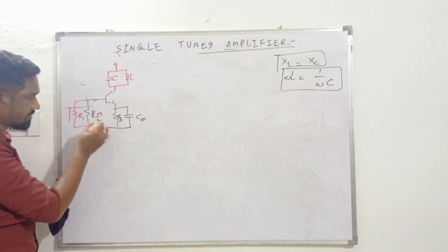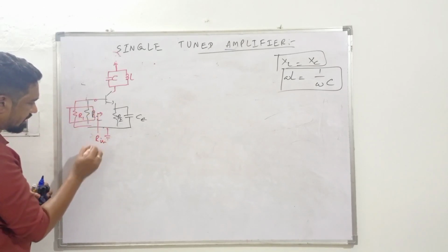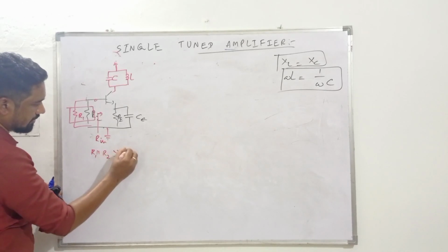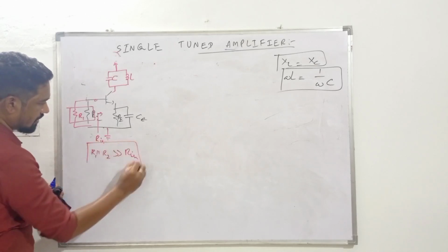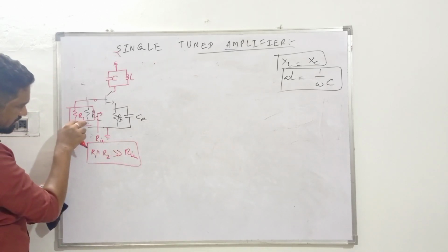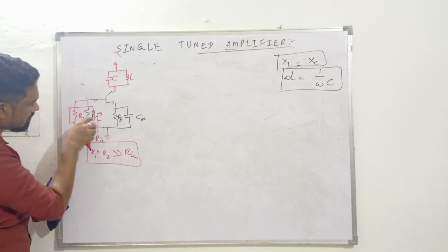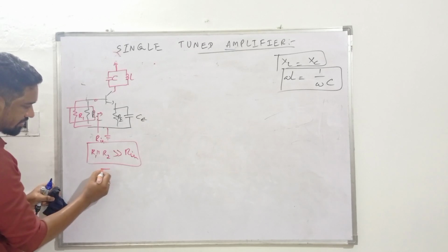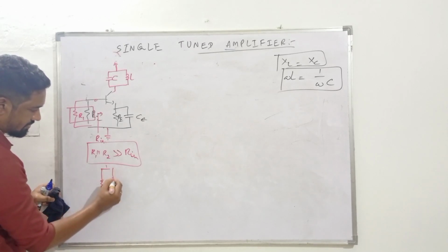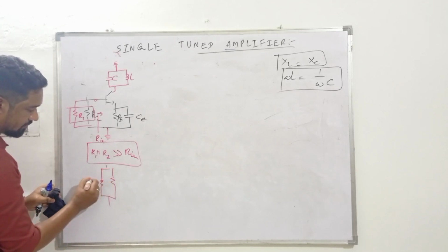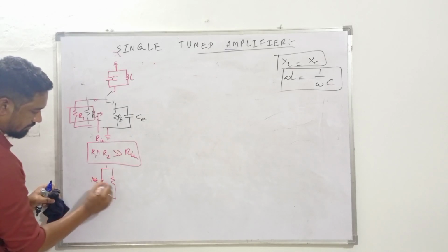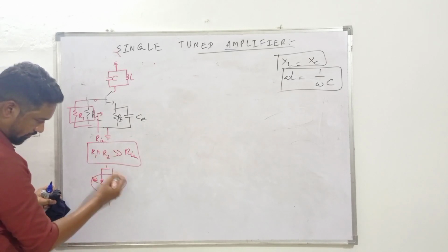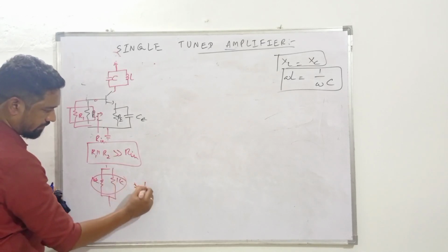These are external resistors, and we can select the values of R1 and R2 in such a way that the parallel combination of R1 and R2 is very much greater than Rin. With this condition, this resistance becomes insignificant when in shunt with Rin, right? Take two resistances in shunt with each other, very different values, 10k and 1k. The parallel combination will be approximately equal to the lower value, 1k, isn't it?